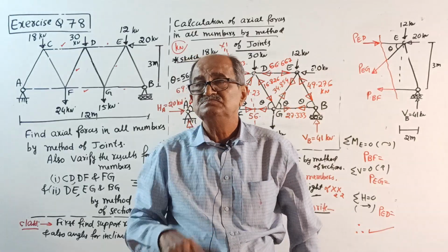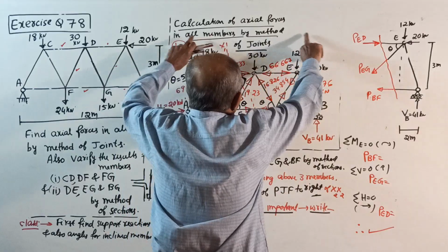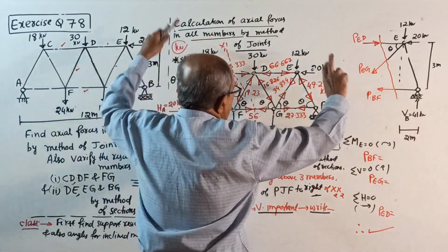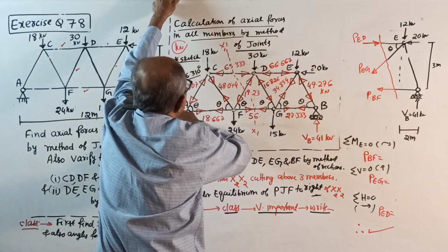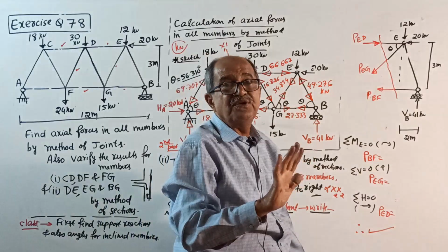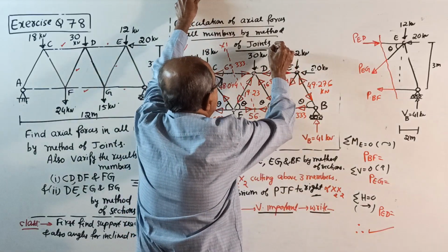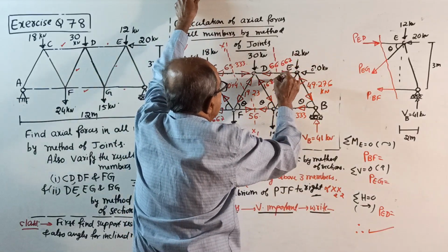Once again, if you are serious, draw the sketch once again. Enter all the reactions and external forces. Do not enter any member forces. Full blank. Then, see, show the cut here. Cut here.